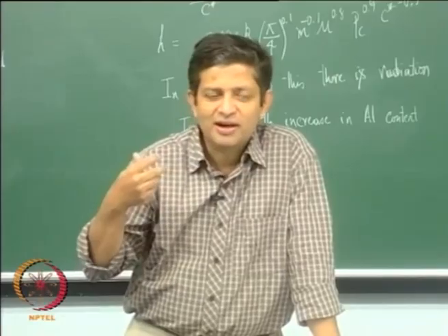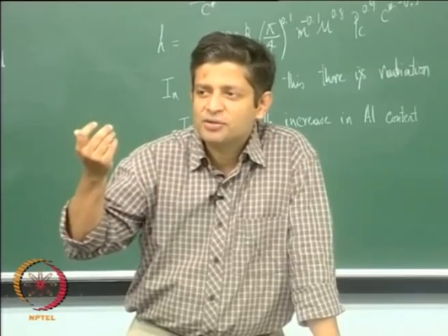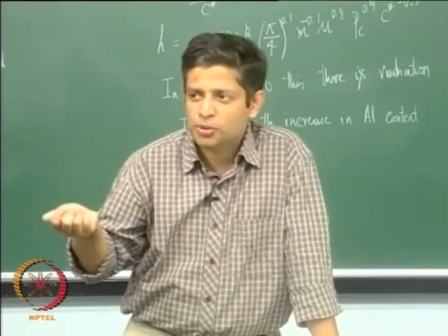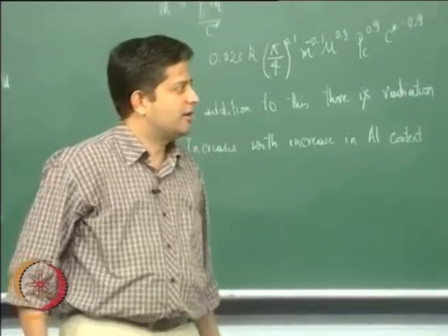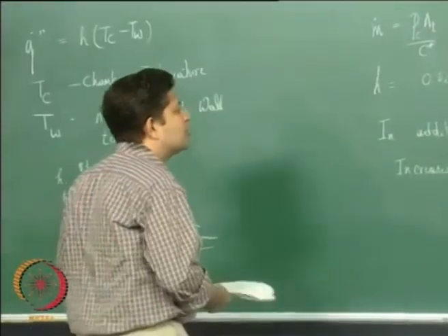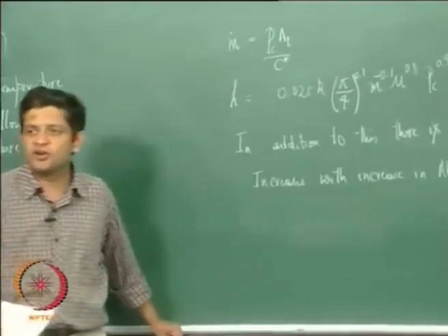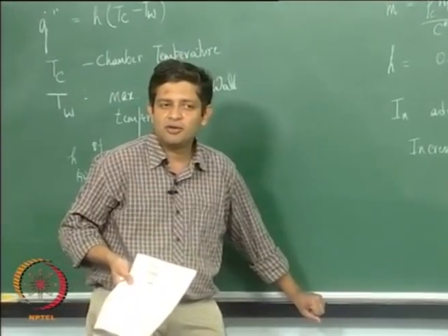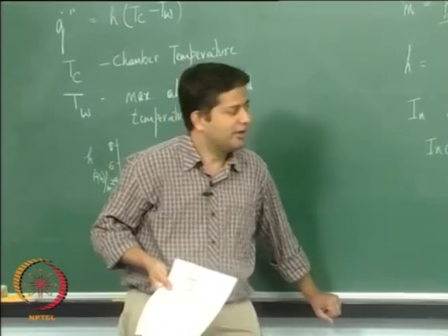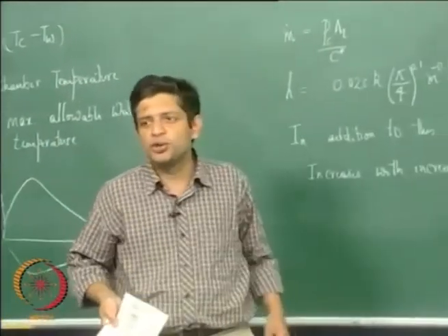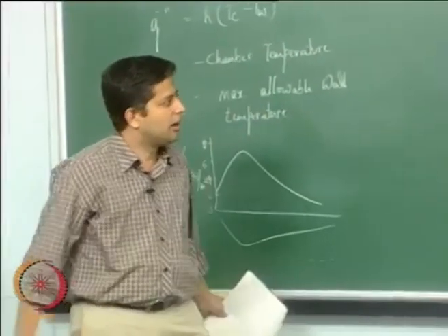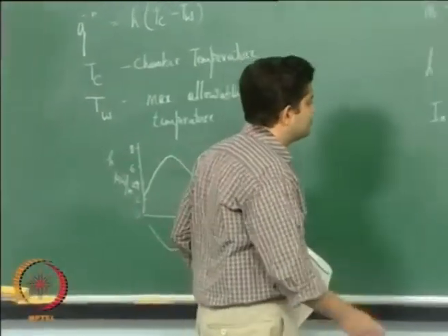The earth re-radiates heat back to space, which gets absorbed by the CO2 and H2O. Now if you look at the gas composition in the exhaust of a rocket motor, it is going to be rich in both these compounds. So you will have both CO2 and H2O in the exhaust, and they add to the radiative heat transfer.